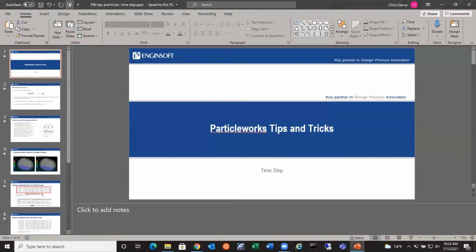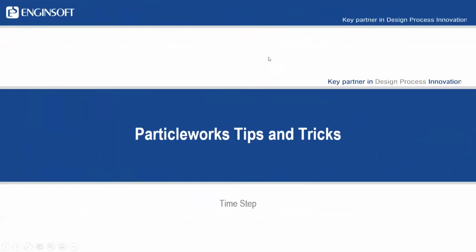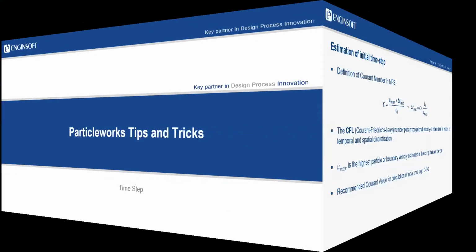In today's presentation, I really wanted to go over some stuff, not so much as fun and exciting as Zach's presentation, but just something that I've seen recently with Particleworks support. As James mentioned in the beginning in his presentation, it's oftentimes easier to create problems than it is to solve problems. And one of the major mistakes that I see frequently, especially with new Particleworks users, is defining the initial time step.